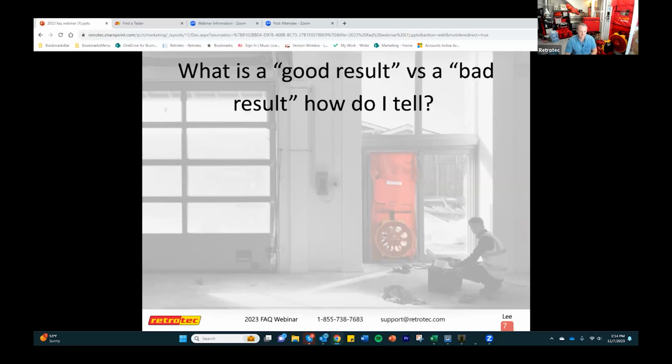So pick a range that the fan has to work fairly hard to get to your target, and that will ensure that your fan pressure is high enough. So the way that the fans work is they take a pressure differential across the range plate. If you're familiar with our fans, they have a B8 plate, for example, on the blower door.